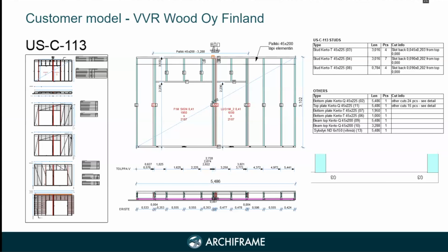The weight is important to know that the element is not too heavy to be lifted at the building site. And you can also include the weight in the schedules. That might also define what kind of crane you get to the building site when you know the weights of the elements.